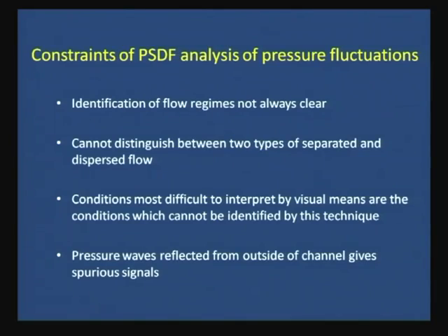What is the next thing? It cannot distinguish between the two types of separated flow. It cannot distinguish between the two types of dispersed flow. This we have already discussed. Other thing is, we can very well distinguish between annular flow, bubbly flow, slug flow under ordinary circumstances. Okay. Only when we have very high flow rates or fluctuating flow, it is difficult.